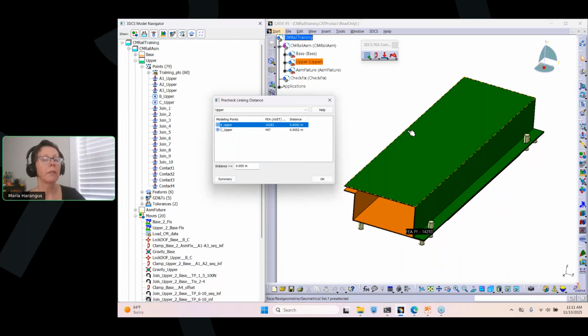The reason for this check is if you have large distances between your nodes and your points, then your deformation may be inaccurate because it may create a lever effect based on the distance between them. When your node translates and specifically rotates due to all kinds of loads you put on the parts, the point will swing around due to the node rotation. The larger the distance, the more it will swing, so your deformation will be inaccurate.